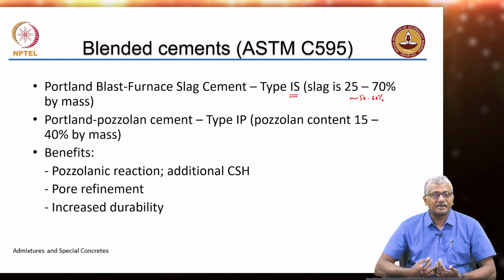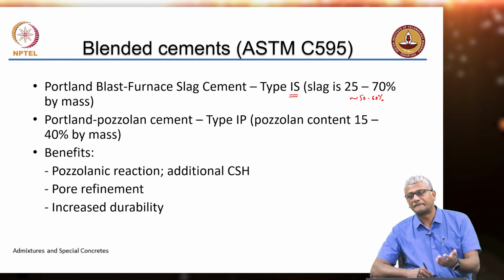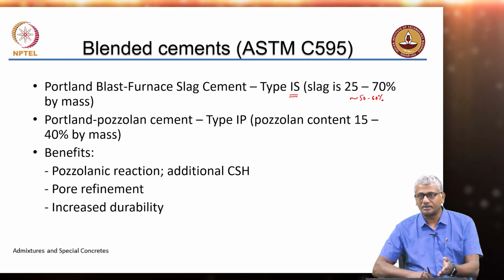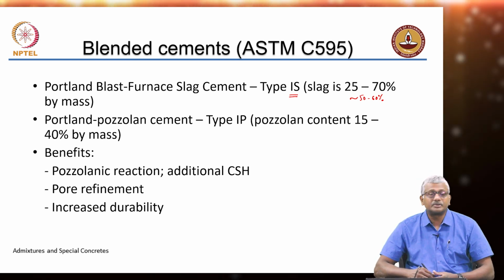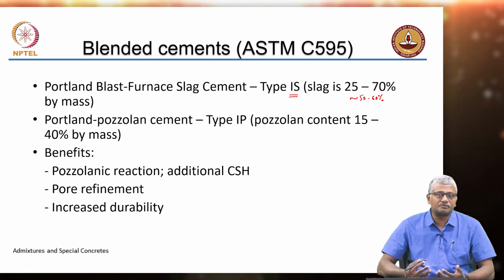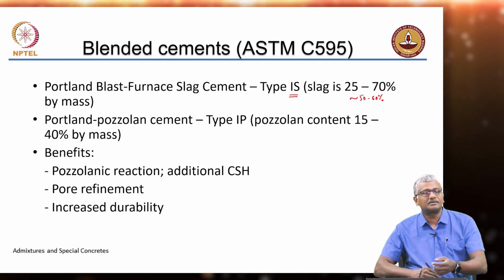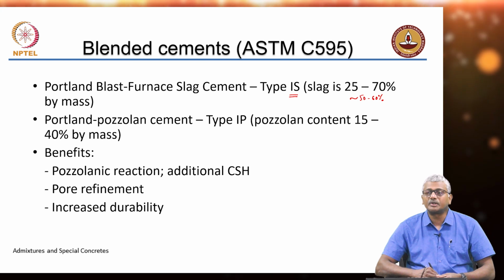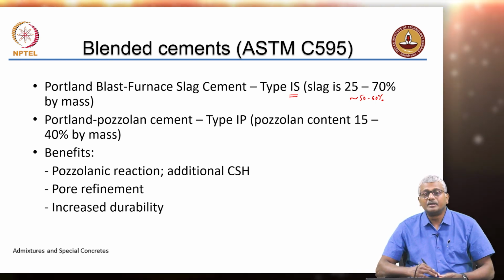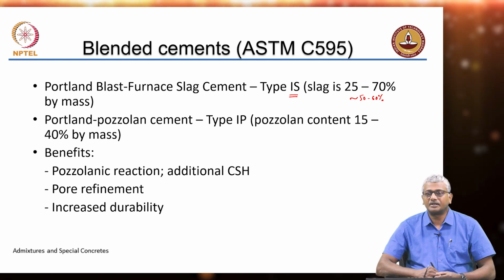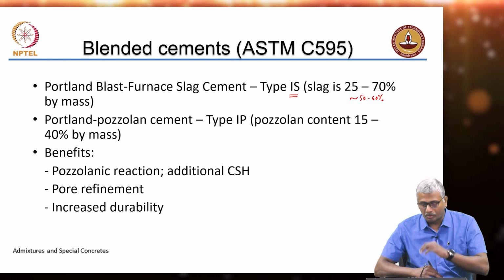So, what does this mean? Again, slag cements will have a net lower CO2 emission potential. Okay. So, it is always of benefit to use slag cement from that perspective, and later when we talk about slag in more detail, you will also learn that it is beneficial to use slag cement from the perspective of higher durability in coastal conditions. We will talk about that later.